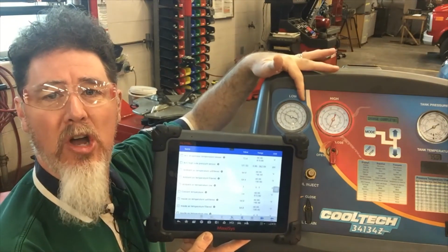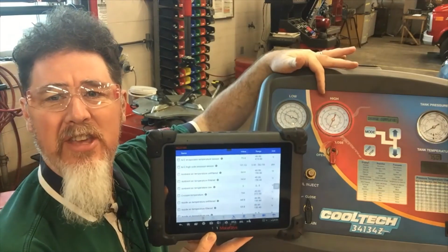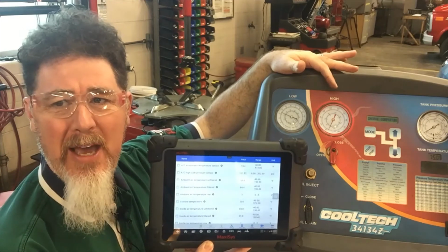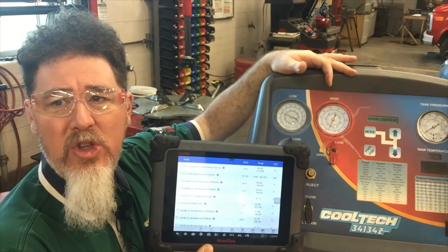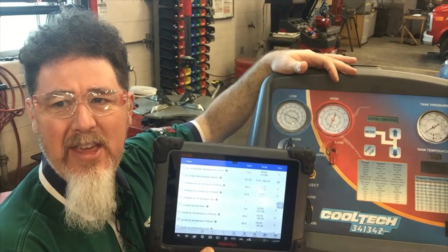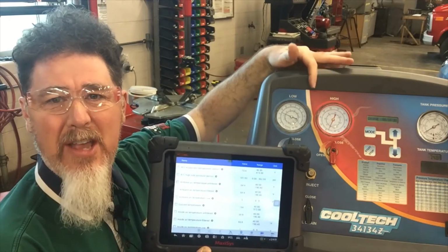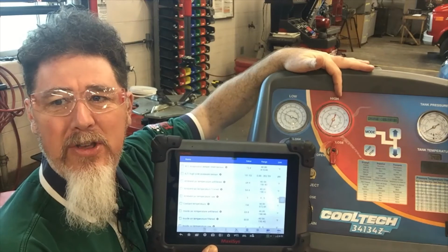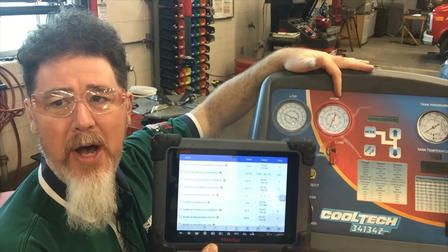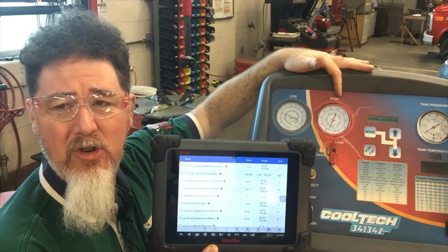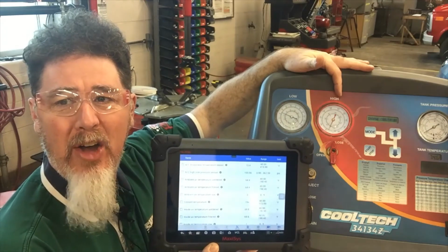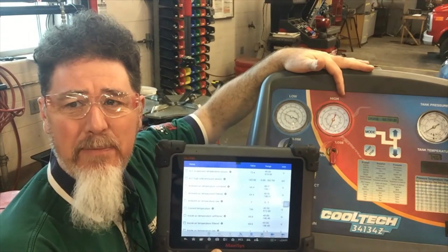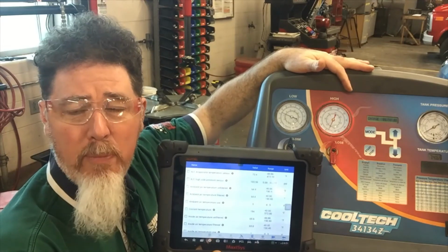But when my AC is on, if you take a look at the high side and the low side gauges, they're both reading around 30 psi. They're reading about the same, which indicates that the restriction is in front of the high side gauge. The actual pressure drop through the condenser and receiver dryer, going from 101 psi down to around 30 psi, is a pretty good partial restriction.